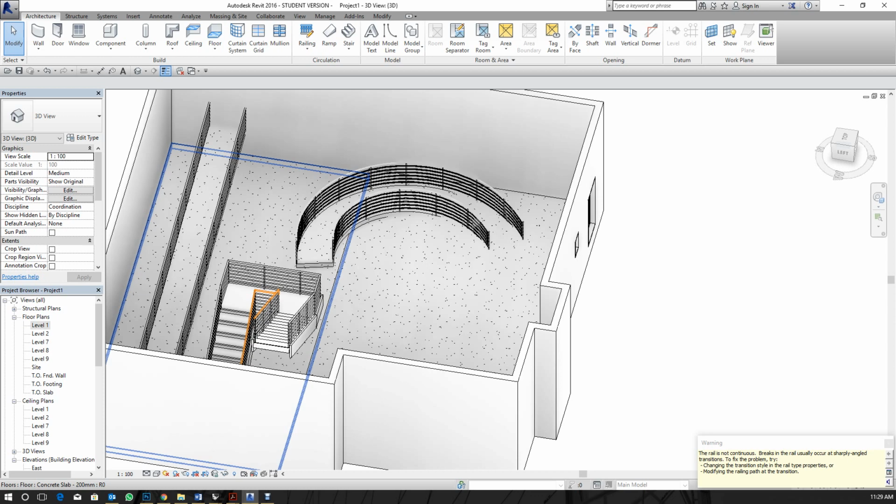You know how to draw a circular elevator? I tried to find it online. You wouldn't draw it, you would model it, and I'm not going to show you guys that now, because that's more advanced stuff than we've covered so far. What I would do is find a pre-made one online, maybe search again, and import it. You can make one in Rhino and import it as a mass and just place it there, right?